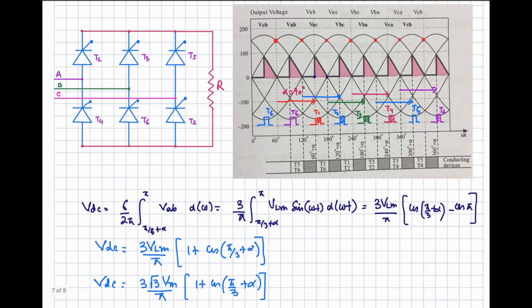Okay, so now quickly moving toward the firing angle of 90 degree. So these are the reference points of the thyristors. So from here at the angle of 90 degree you will be applying the first pulse. So that is this one. You are going to turn on thyristor T1. The reference point for the second thyristor is this line. So from here you can see 90 degree. This is the pulse for the second thyristor, and similarly from this point at the angle of 90 degree, third thyristor, fourth, fifth, and so on. So you can refer to the last video for the detailed discussion of this one.